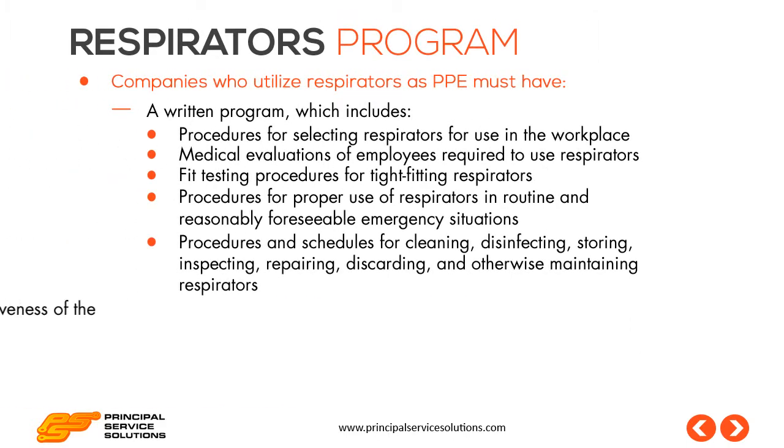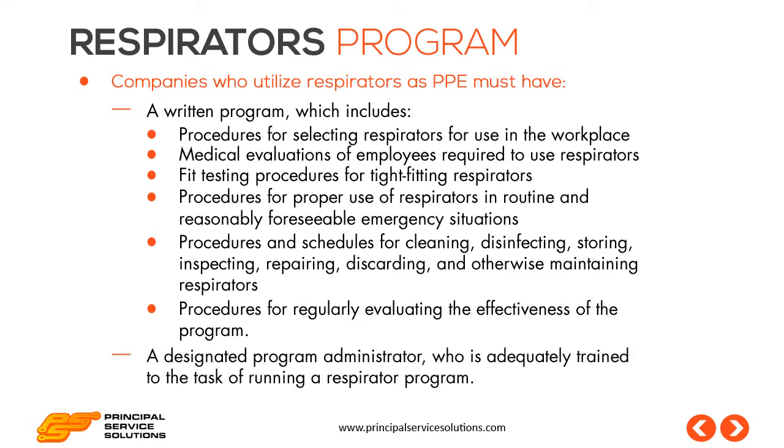Companies who utilize respirators as PPE must have a written program which includes procedures for selecting respirators for use in the workplace, medical evaluations of employees required to use respirators, fit testing procedures for tight-fitting respirators, procedures for proper use of respirators in routine and reasonably foreseeable emergency situations, procedures and schedules for cleaning, disinfecting, storing, inspecting, repairing, discarding, and otherwise maintaining respirators, procedures for regularly evaluating the effectiveness of the program, and the company must have a designated program administrator who is adequately trained to run a respirator program.